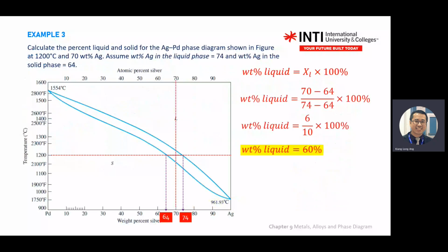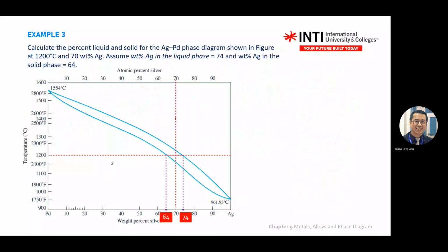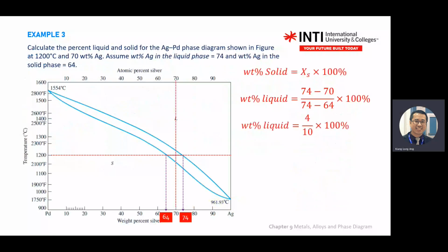You find the length between the X and the solid. That one is to calculate the other one. Here to solid is to calculate liquid percentage. Then here to here, because this is liquid, is to calculate the other side, the other type, which is the solid one. Understand? Okay. The rest is the same. Okay, so I flip back.